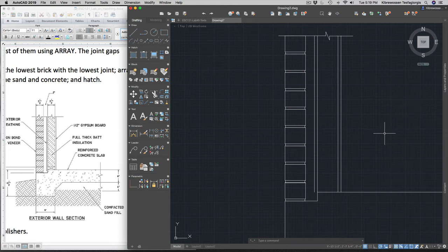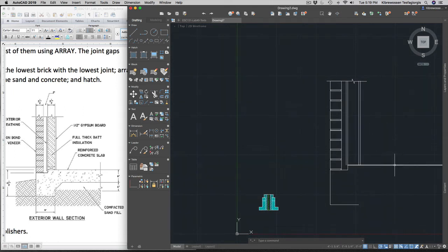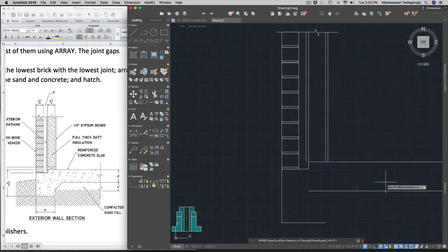Then what else is left? Then the thickness of this slab is 6 inches. You can go down to offset by 6. Okay. And then there's a 4 down. So you're going to go ahead and offset this line by 4. Which line? This line. See? Once you do that, then you draw a line that runs from here.